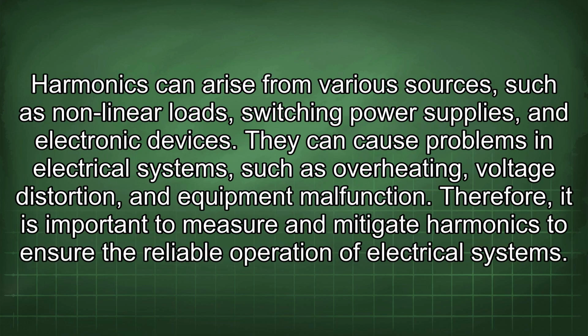Harmonics can arise from various sources, such as nonlinear loads, switching power supplies, and electronic devices. They can cause problems in electrical systems, such as overheating, voltage distortion, and equipment malfunction. Therefore, it is important to measure and mitigate harmonics to ensure the reliable operation of electrical systems.